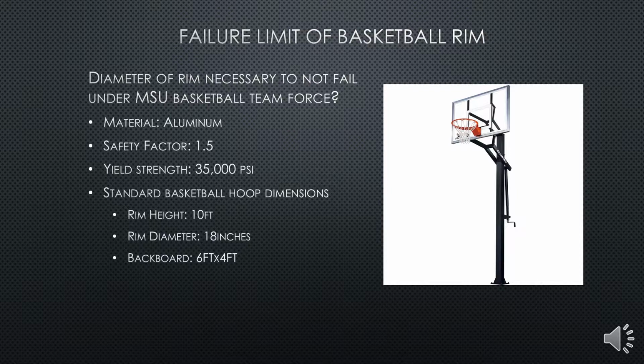Once a force is applied on the rim, if the hoop experiences a stress of over 35,000 psi, it is considered a failure. We will be testing the rim with varying cross-sectional diameters to see where the failure point is.